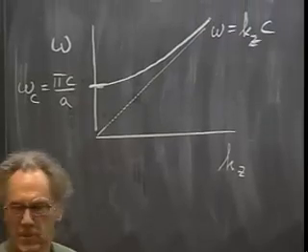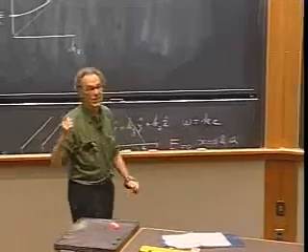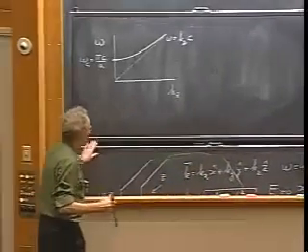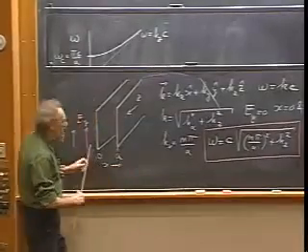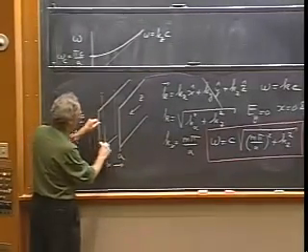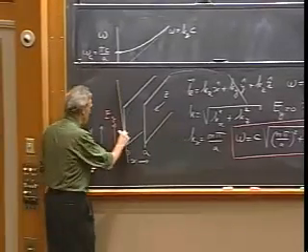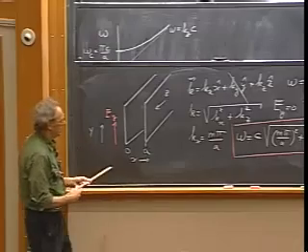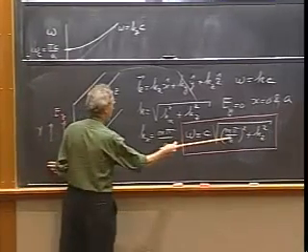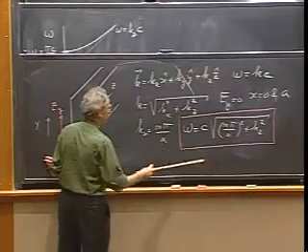So no frequency below that value can propagate through the gates, so to speak, through the opening, because it cannot meet the necessary condition that the E field becomes 0 here and 0 there, which is non-negotiable. It has to become 0 here and 0 there because it's an ideal conductor. So K of x must obey this boundary condition.